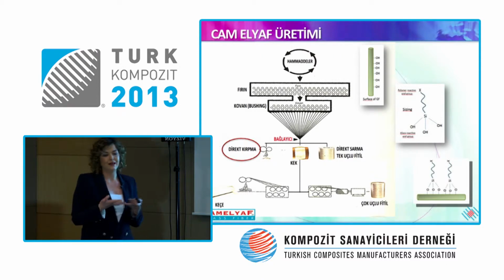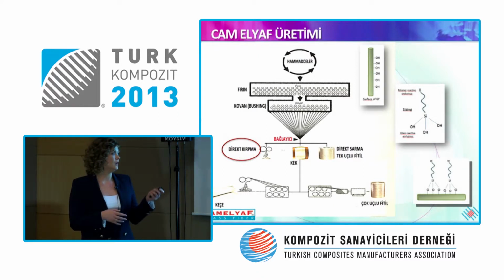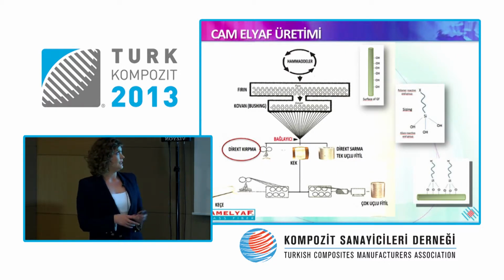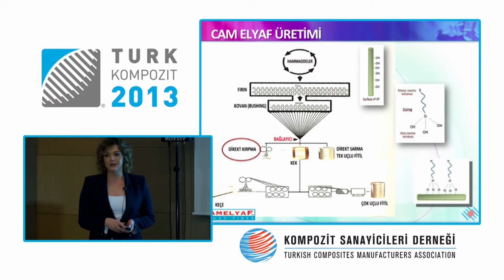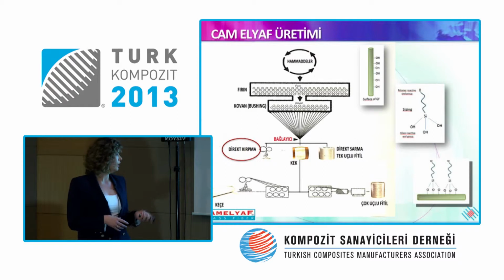This takes us to the bushing process. This is actually a filtering process. It's like a strainer, and they will reach a certain fiber form at a certain thinness. And once they reach this stage, they will have hydroxy groups in them, which will be prepared for reactions. Later we have the bonding application, which is the heart of the process for us. Here we have silane-based organic materials, and with the glass fiber, this is going to be the bridge for the matrix, and it's going to have this chemical composition.